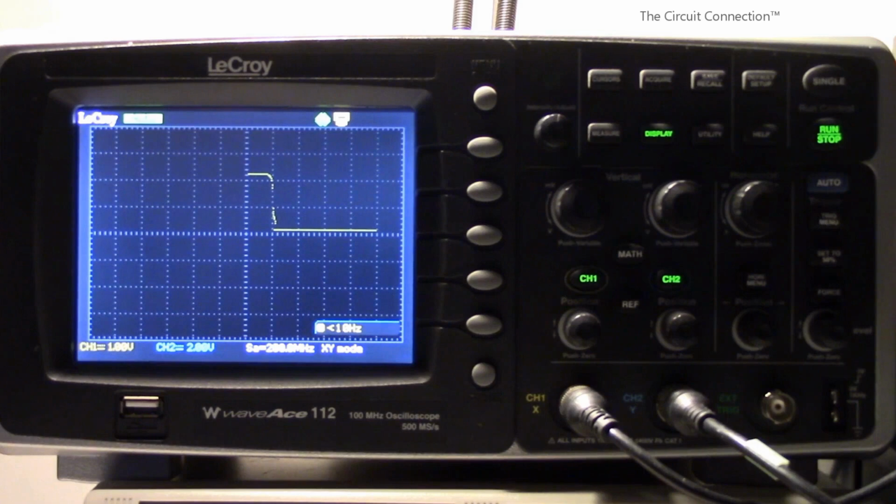So overall, everything was very accurate, and the only thing that was a little off was Vin high, but that's okay because it actually made our noise margin even larger than we would expect. Vin high versus Vout high, the difference between 2.7 and 2.0 is 0.7 volts, but actually our Vin high is closer to maybe 1.2 or 1.4 volts. So 2.7 minus 1.4 is larger than 2.7 minus 2.0. So we actually got a slightly better characteristic than we would expect concerning Vin high. Okay, so let's go ahead and get back into the oscilloscope analysis.